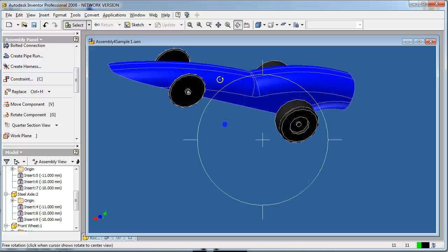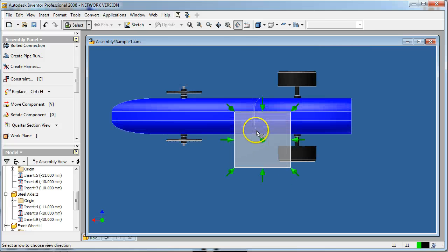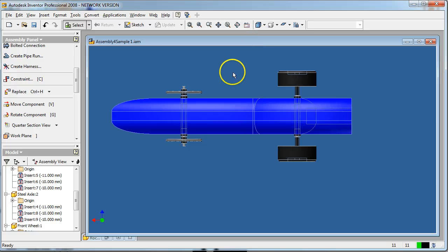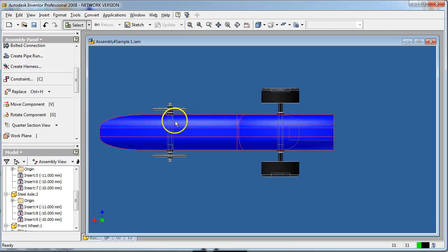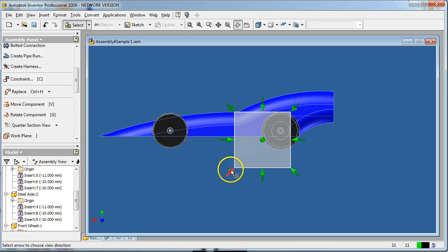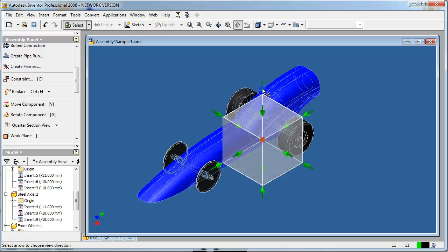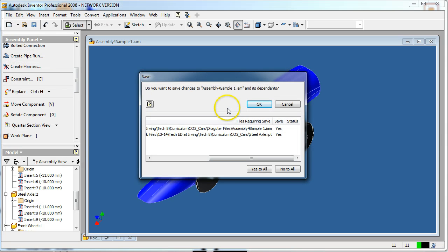Last thing I could do then is to rotate it so that we're looking down on it. Aerial view, the top view. And we're going to go into the hidden view, hidden lines. Everything looks good, ready to go. And that is a completed, assembled drawing. So rotate it back if you want on an isometric view. Pull it back into no hidden lines. And from here, save it. Make sure you save once again, and that'll be your finished product.